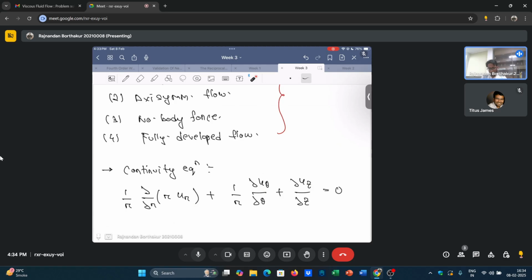Okay. All right. Now can you tell me, based on the assumptions, which are the terms that straightforwardly go to 0? Can you tell me? Del uz by del z. Yeah, exactly. This term goes to 0. That is because of the fact that your flow is fully developed. That is something that we wrote. What happens to this term? Is it 0 or a non-zero quantity?